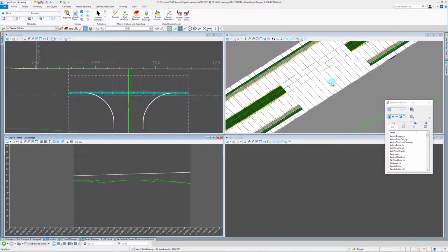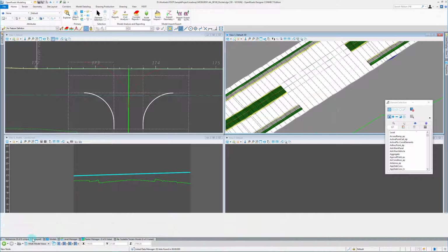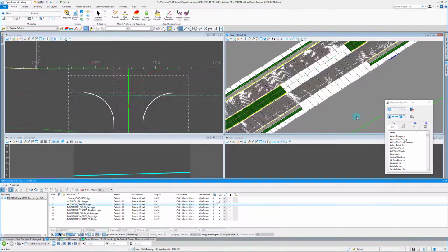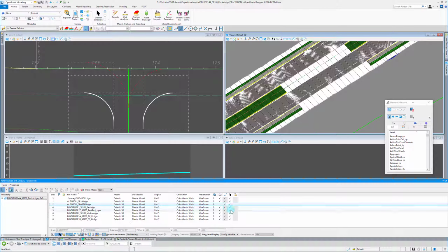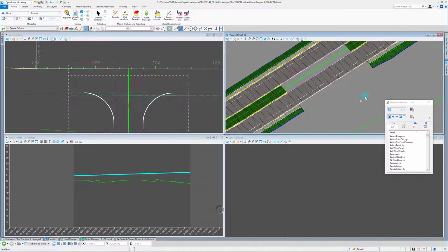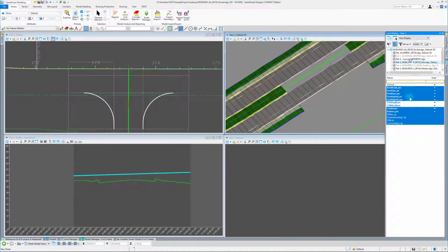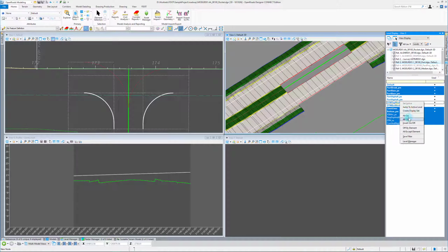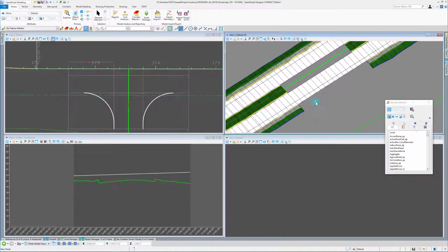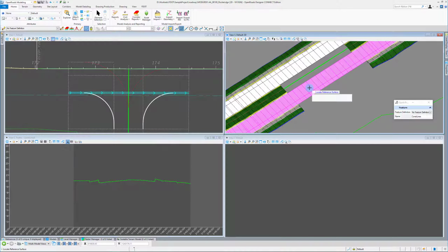The reason I use this projection is because it doesn't always work out if we were to use, let's turn the projection off and the pavement back on. Oops, gotta get in here. So I want to turn the projected off, and let's turn our pavement back on, pavement asphalt. We're just going to turn off everything but the top mesh. So I want to try and get a quick profile from surface from that. And it may work, it may not, but it doesn't always.